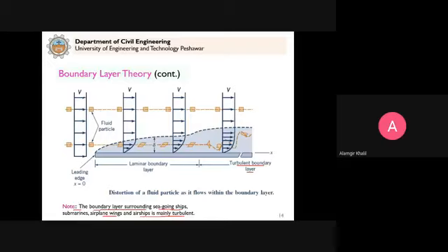So now in this case you can see the behavior of a fluid element if we have undisturbed flow. The fluid particle element that we consider here just moves in a similar fashion at the top. Means there is no rotational effect, no change in the shape, no deformation. That's why we say that the fluid outside this boundary layer is treated as inviscid flow.